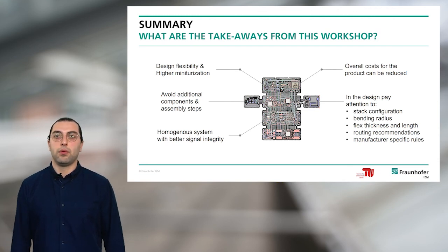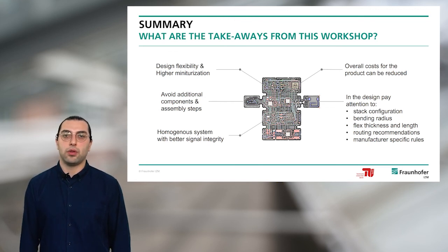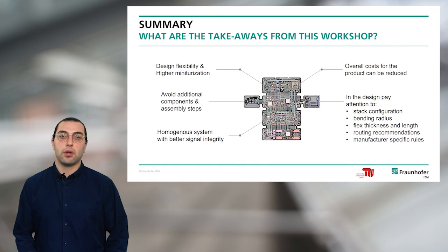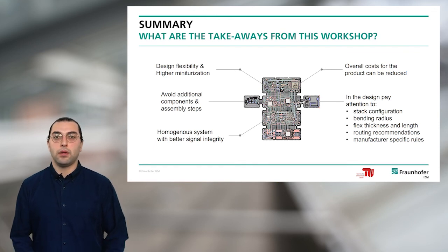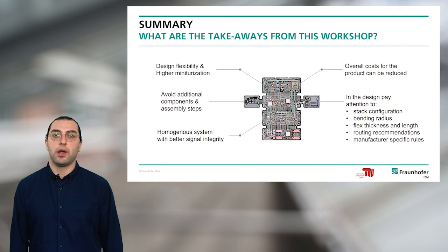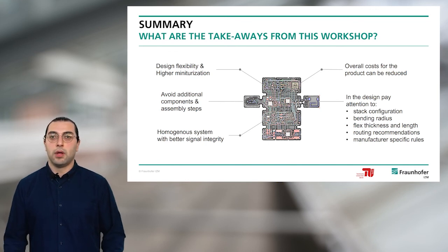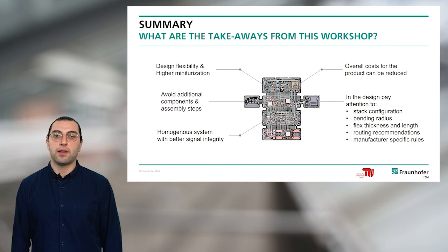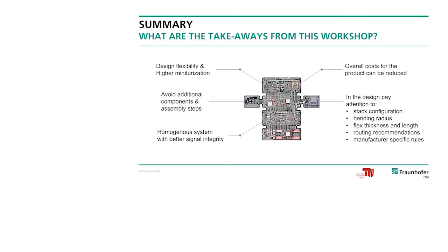And if you design rigid flex, pay attention to the stack configuration, the bending radius, and flex thickness and length. There are formulas which I gave you in the slides. Take care of the routing recommendations of parallel and perpendicular routing in the flex part, and also take care of the manufacturer-specific rules. So thank you for your attention. I look forward to your questions.